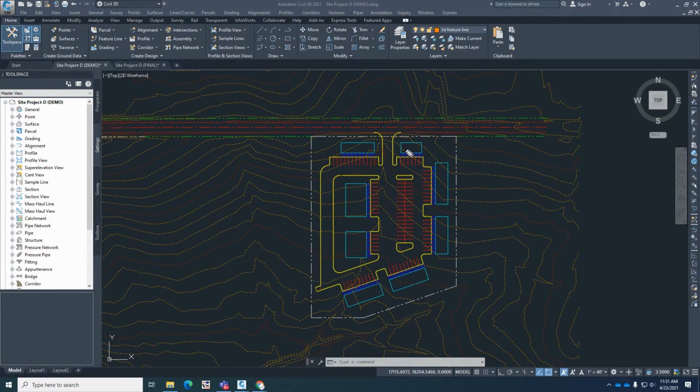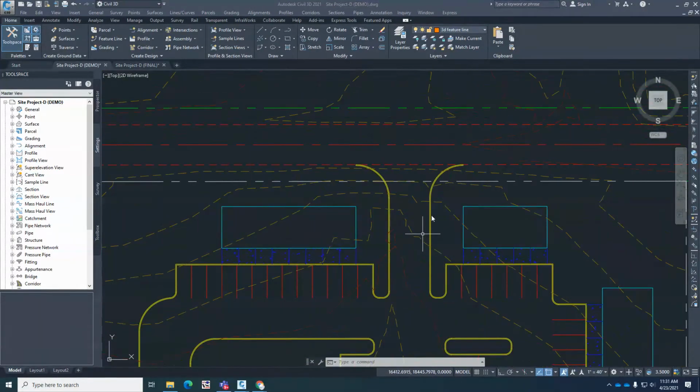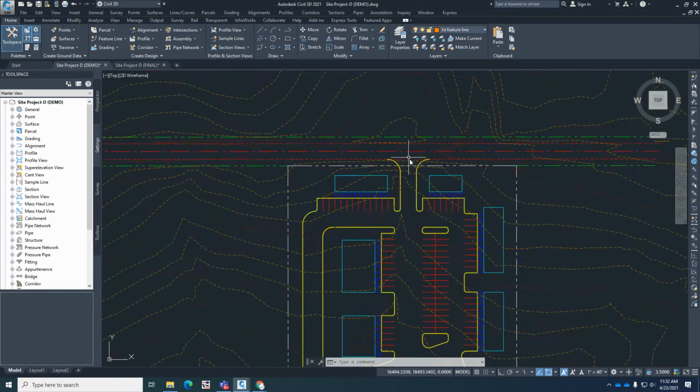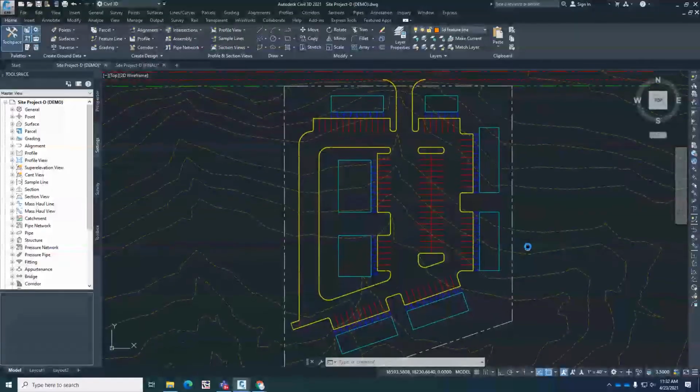Okay. There is going to be a little bit of a high point in here that we do need to address, and that's where I will make a demonstration in this video to show you how to create that high point. Since everything's kind of draining in this direction anyway, we really don't want runoff from the roadway to drain here. So I'll show you how to create what's called a high point, so that naturally the water will drain away from it. The high point we're going to create is going to be at the property line. So water will drain here back to the roadway, and from the property line back into our site. I will show you a demonstration in this video series on how to do that one. But other than that, that's pretty much what we're going to be doing.